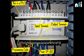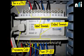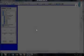Now you can see some indications here. When the PLC is on, you can see a green light. When it is running, you will see a green light again. When it has some fault, there will be an orange light over here. And when there is a force input, in which we are driving the input from inside the software instead of switches, then there will be a force light here. So these are the basic components of what a PLC is all about.